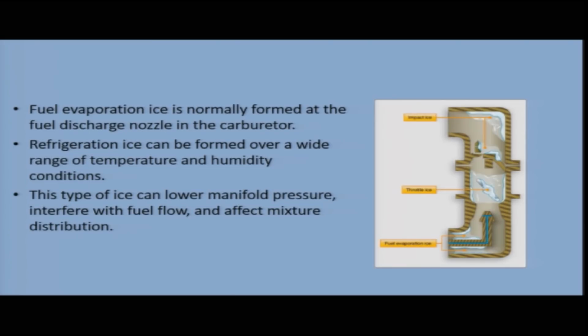This fuel evaporation ice, or refrigeration ice, can form over a wide range of temperatures and humidity conditions. Since the engine operates in various climatic conditions, the ice will form over a wide range of temperatures and humidity. This type of ice can lower the manifold pressure, interfere with the fuel flow and also affect mixture distribution. So, this is not a desirable quality.